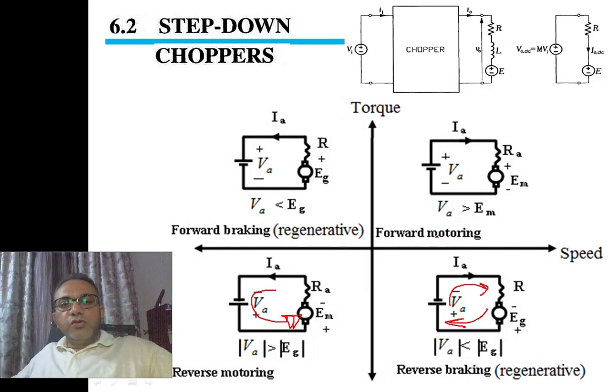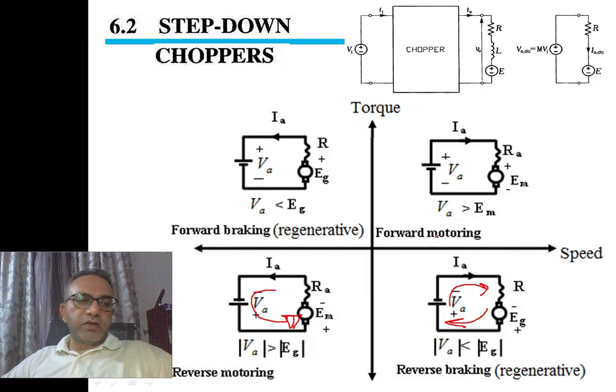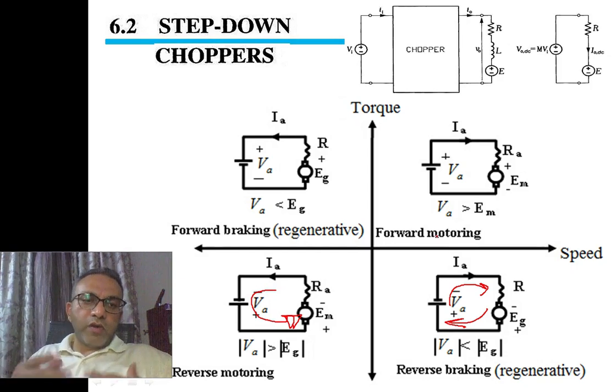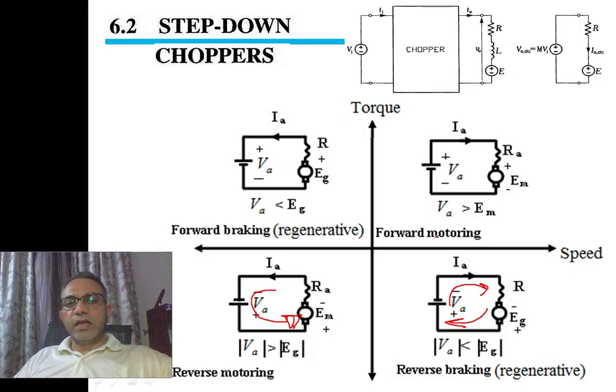So we need a universal DC-DC chopper, or DC-DC converter, which will give us the freedom of stopping the motor, controlling the motor, and reversing the speed of the motor. Hence, this is the requirement, and after this slide we will come to the circuit which implements the universal DC-DC converter, which operates in all four modes.